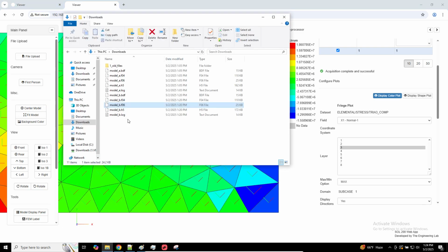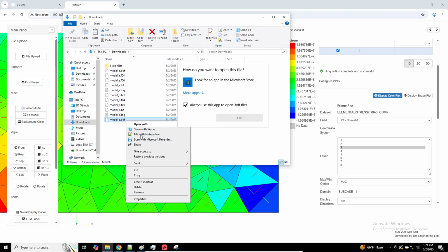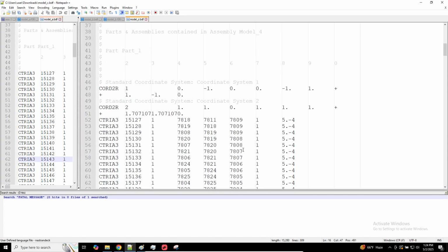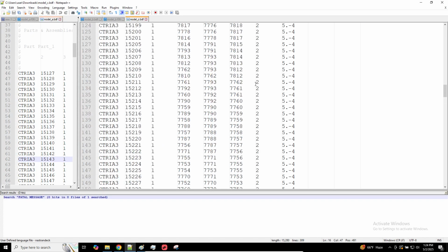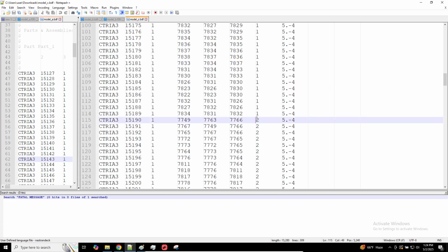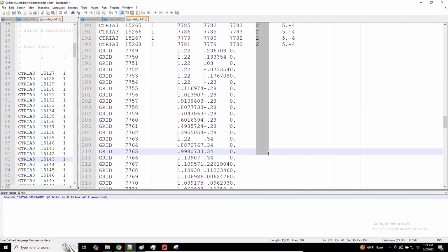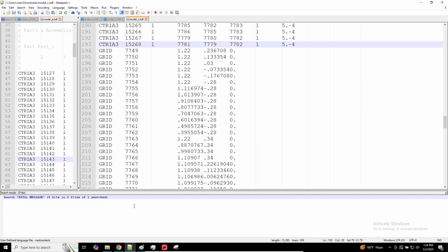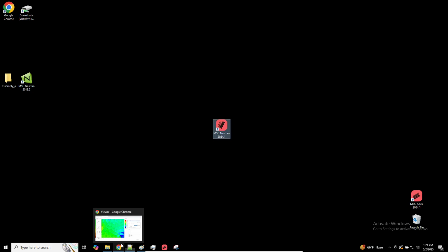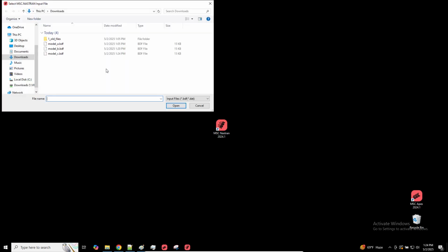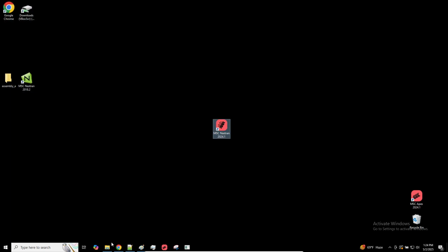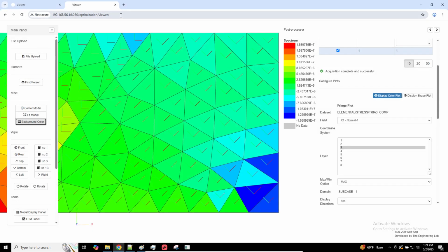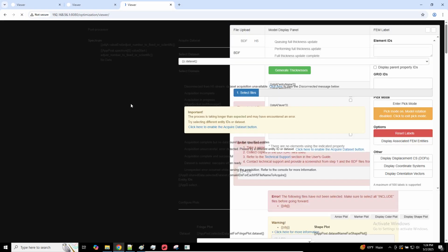Now, let's do one last modification. Let's go ahead and copy this here and here. So we're going to copy and create a third model. Let's go ahead and put that here. And I'm going to modify this 2. I'm going to make this maybe a 1. Save that, and let's rerun this with Nastran. Okay, let's go ahead and open a separate window now.